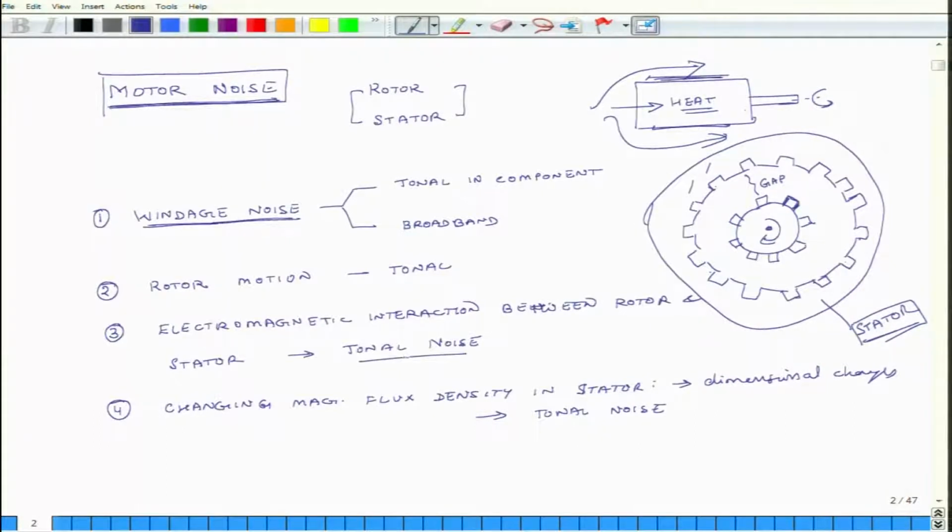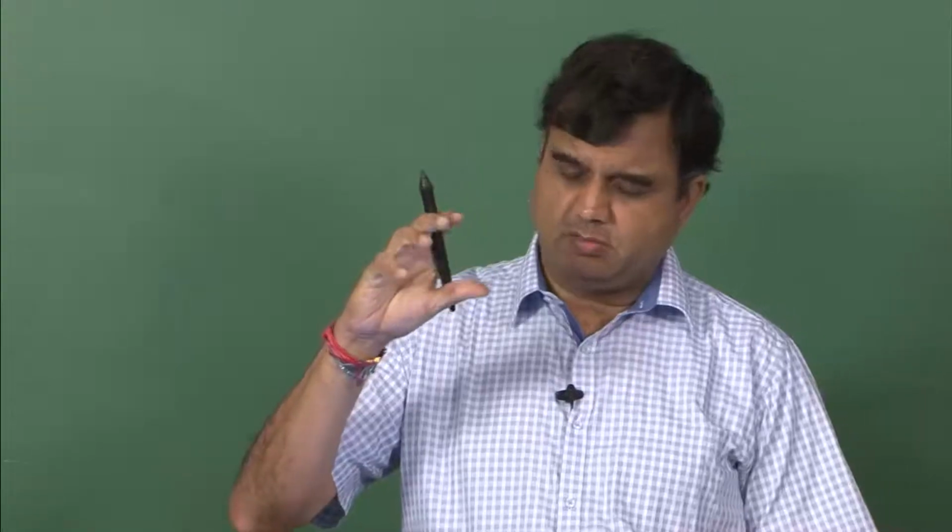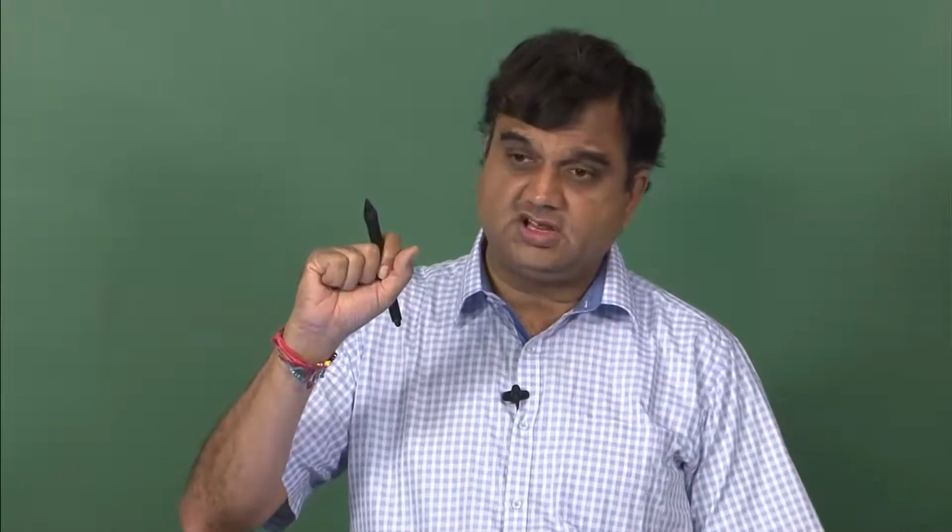See, this first guy, it was not about expansions and contractions, rather because the rotor is moving inside the stator, sometimes it comes close, sometimes it goes away, and when it comes close it experiences larger electromagnetic forces, because of those forces it is rotating, and so these forces, because of electromagnetic interactions, they are also changing cyclically. So, that is why this noise gets generated, and this noise gets generated because ferromagnetic particles, materials and elements, they shrink and expand, and as they shrink and expand, noise gets generated because it pushes out air.